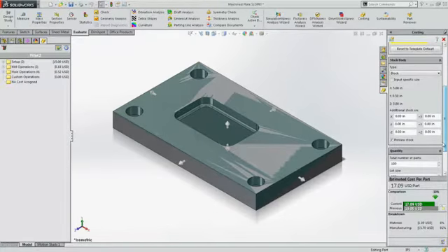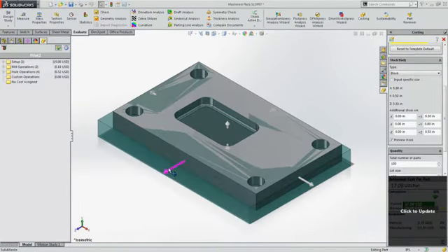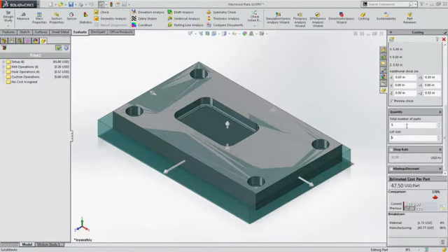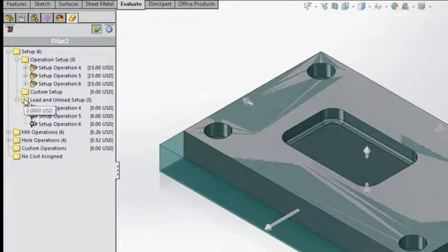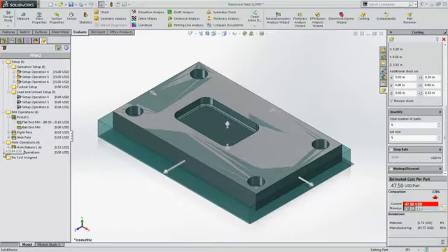You can also drag the stock size if you want to mill the sides or if stock sizes are limited. And just like Custom Part Net, you can specify the run quantities. And the really great part of SOLIDWORKS costing is that it explains in detail where all your costs are coming from in the Property Manager. It lists each feature in the part automatically and correlating it to its particular manufacturing operation and associated costs.